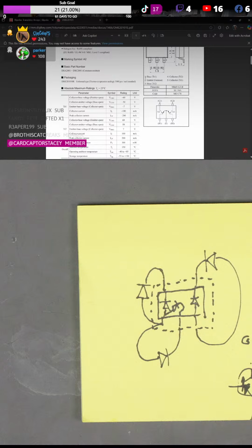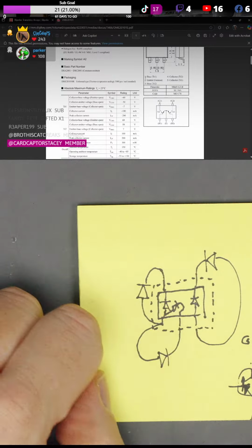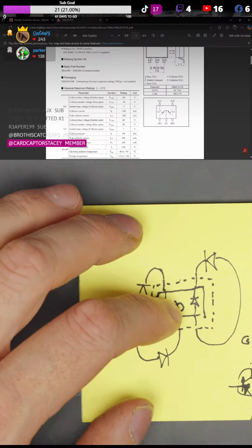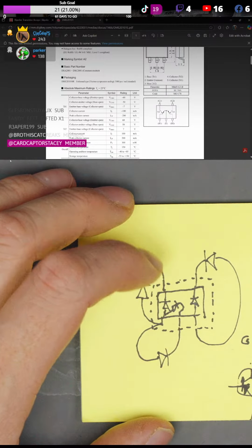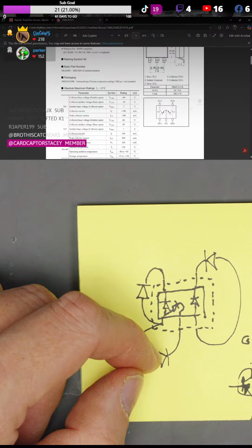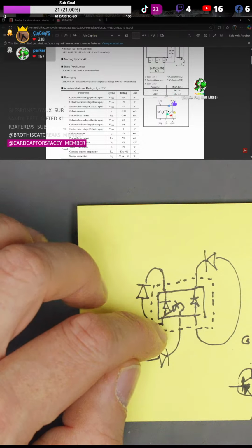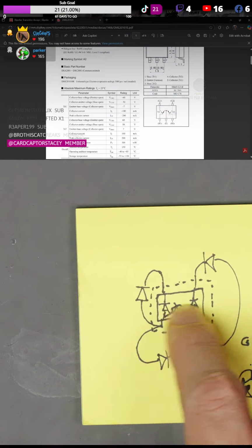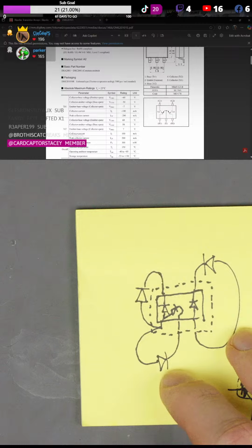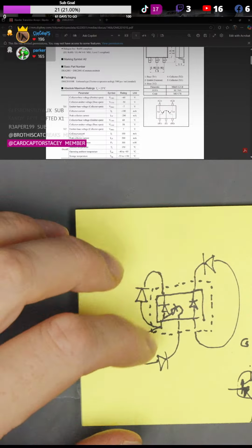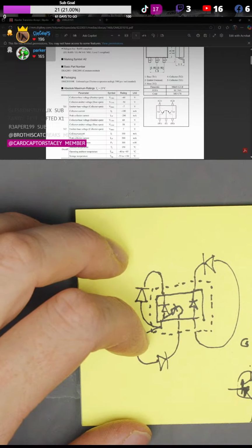I mean, you could have the most obvious thing, which is literally 3 diodes in a package, and you've just done a Q designator. There could be nothing else in this package. It could literally be 3 diodes. But then you don't even get triple diode packages anymore, so you wouldn't even find this or know this. I'd maybe have to put this in a component tester and test every combination of 3 pins to see if it picks up that there's current flowing through one. And if it notifies and figures out there's a transistor, that's probably what it was.